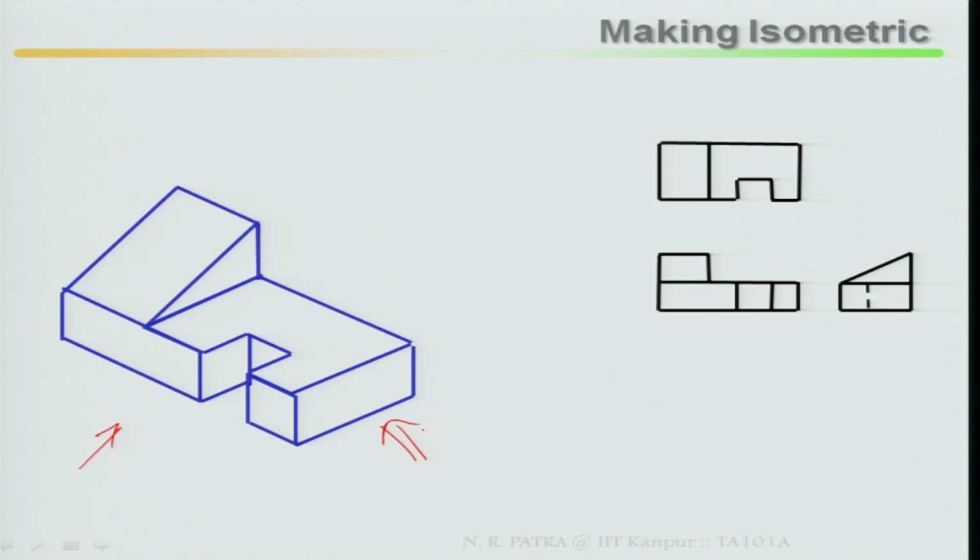Now look at the front view. If I am looking from this side, these lines and these points are merging, this merging, this merging. Once they merge, how does it look? It looks like one line, the other line. Because this side I am seeing, I can see these two points. In this case, this point and these points are going to merge, right? Once they merge, this slanted surface will completely vanish in the front view. So you are going to see only this kind of surface.